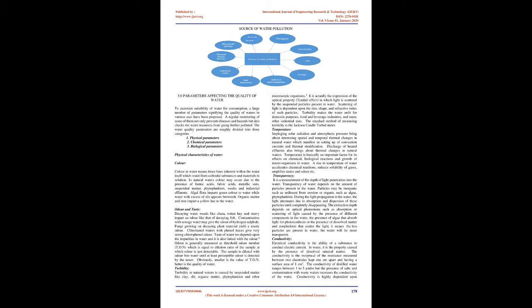Total dissolved solids, TDS, are due to soluble materials, whereas suspended solids, SS, are discrete particles which can be measured by filtering a sample through a fine paper. Settleable solids are those removed in a standard settling procedure using a 1-liter cylinder. They are determined from the difference between SS in the supernatant and the original SS in the sample. The WHO international standards set the permissible limit for dissolved solids as 500 mg/L.